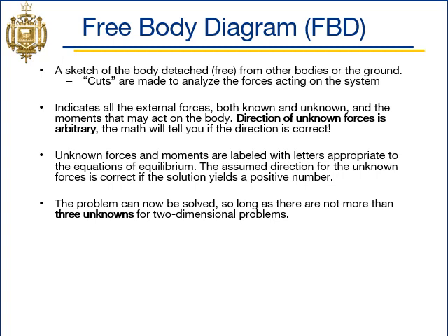So you make a cut in the system, and then you analyze the forces in that system to make sure it's in static equilibrium. Important on our free body diagram, they need to indicate all the external forces, both known and unknown, and any moments that might be acting on the system. If we have some known forces, we need to make sure that those are on there. And if we have unknown forces, we need to make sure that those are also listed on there with some type of label so that we can solve for them.